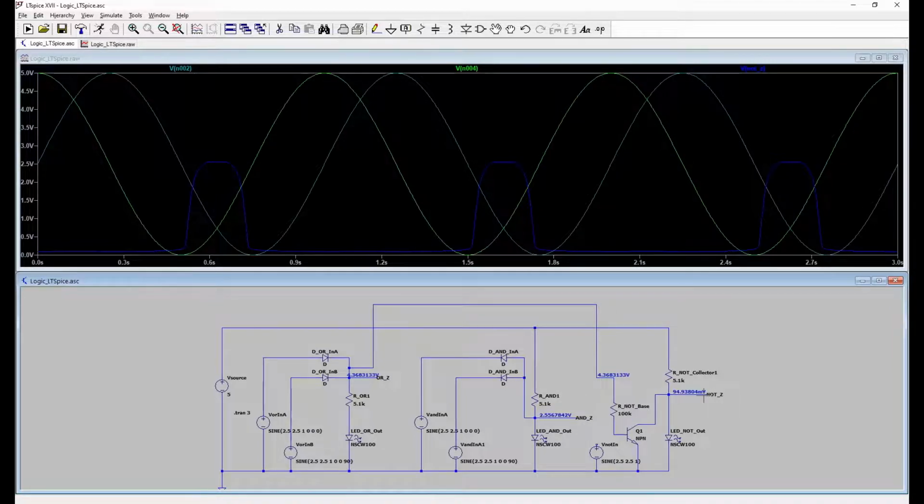And looking at the cycle, we can see that the output is high until one or both of the OR inputs goes above 1.4 volts and then begins rapidly dropping towards 0, stays 0 until the voltages at input A and input B both drop below 2 volts.